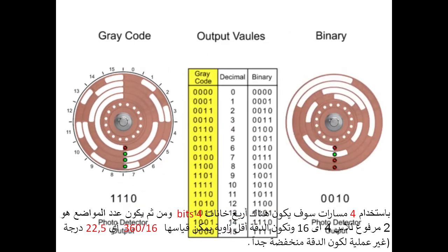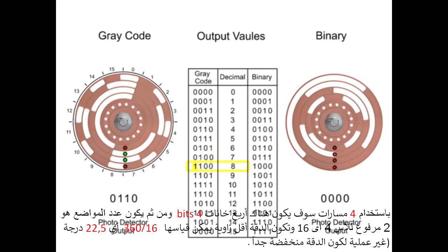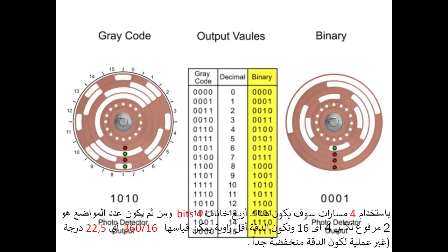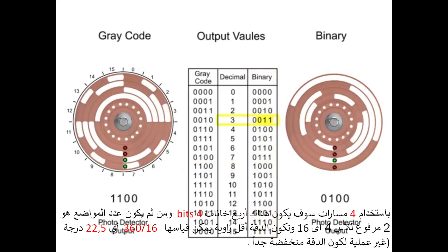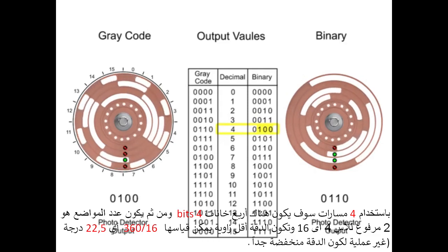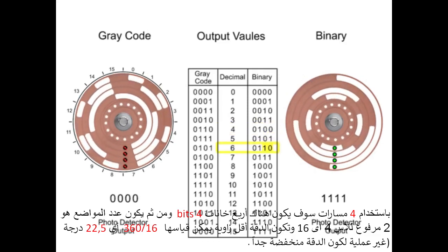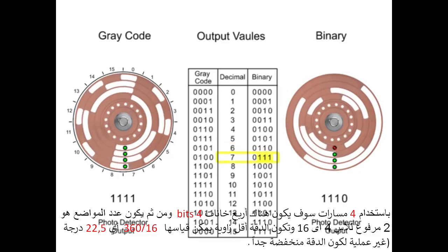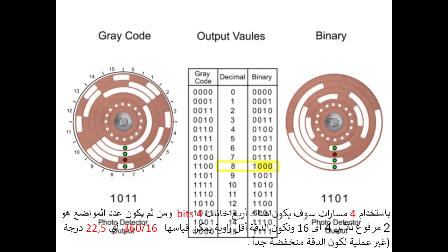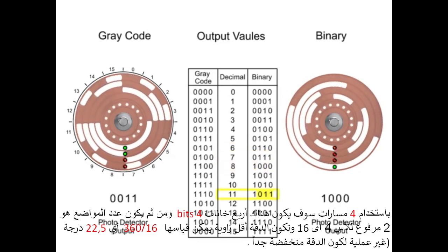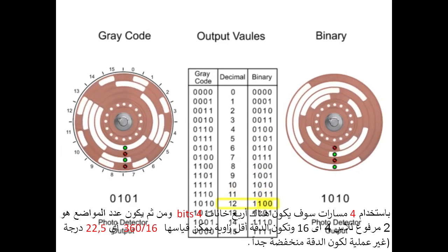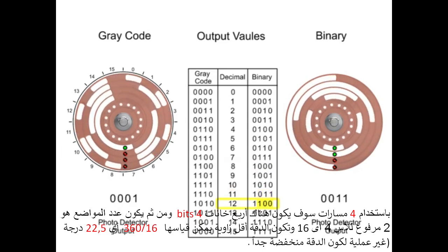Gray code is designed so that only one bit changes at a time, contrary to a binary system where one or more numbers change in the word. By changing more than one number of the word at a time in the binary system, the possibility of positioning errors is greater, making gray code the preference in precision applications.